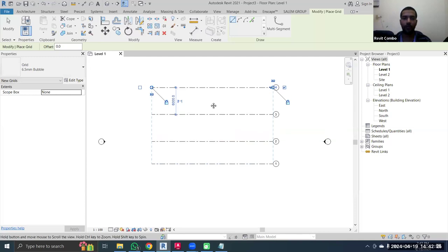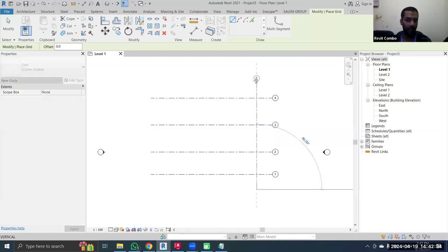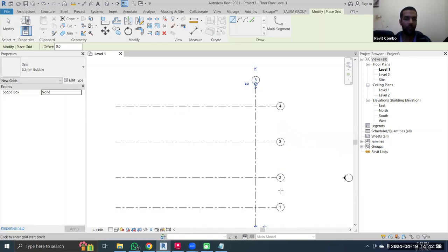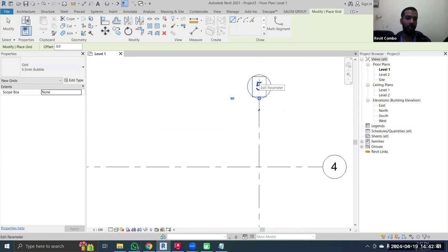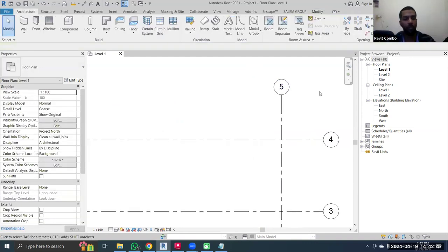So you have a third point, so you can place a third or a fourth, something like that. Now just place them. And if you want to place them vertically, you can also start from somewhere here, and it's going to be vertical. But when you place vertically, rather than numbers, you're going to have letters like A, B, C, D or something. To have A, B, C, D, you can escape your command, escape, and you can see that now your cursor looks like an arrowhead.